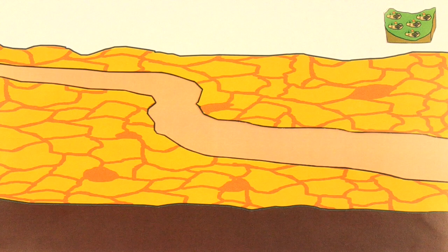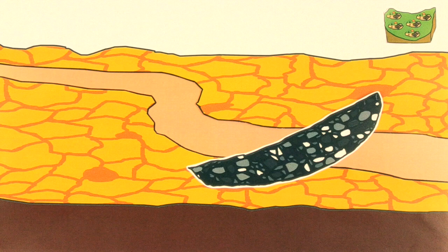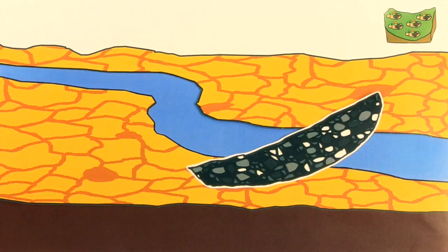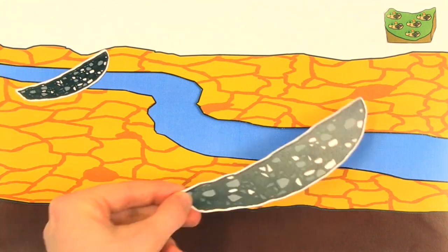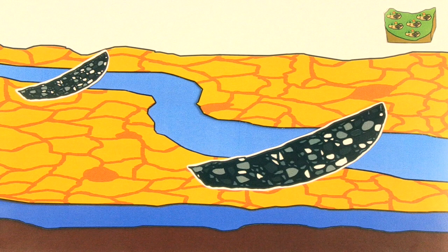In streambed systems, structures such as sand dams or check dams are constructed across temporarily flooded channels. They are built from upstream to downstream to reduce the force of the water flow, to infiltrate water, and to control erosion.